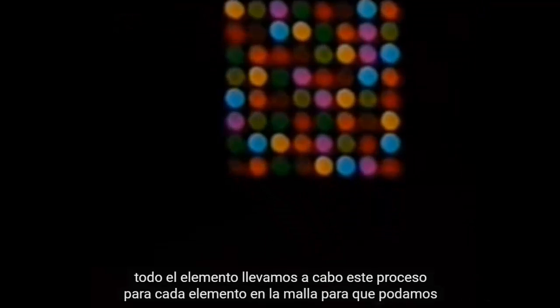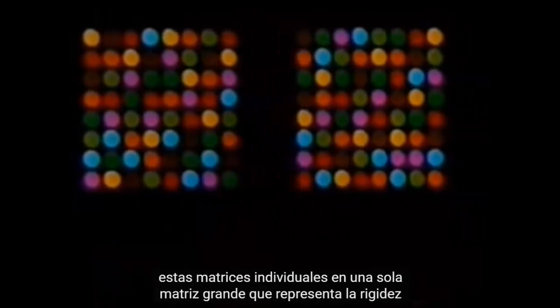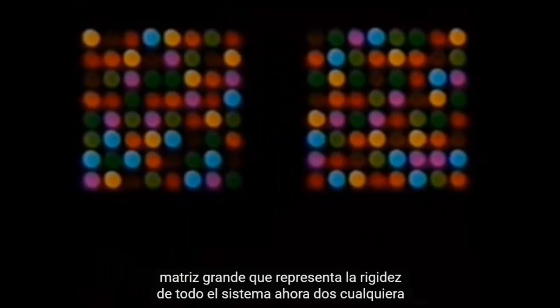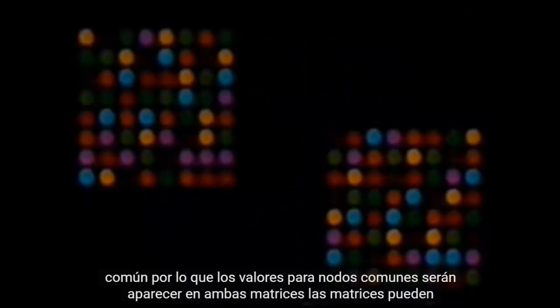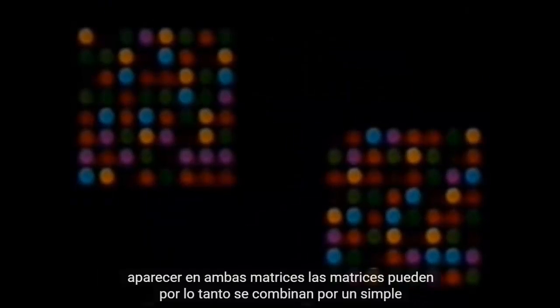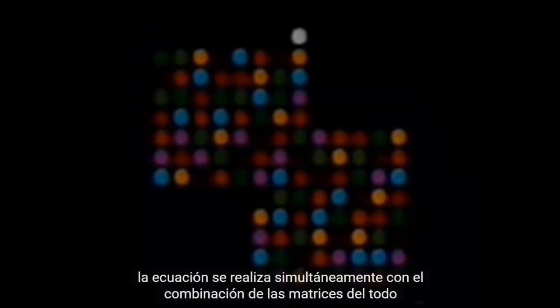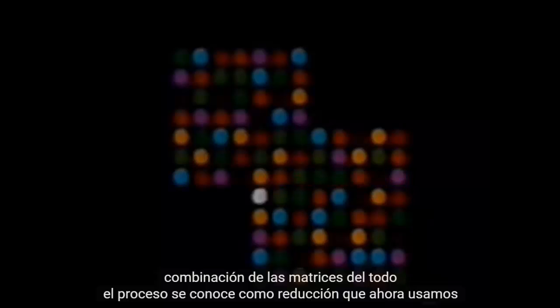We carry out this process for every element in the mesh, so that we now have a stiffness matrix for each one. The important step now is to combine all these individual matrices into a single large matrix representing the stiffness of the whole system. Now, any two neighboring elements will have nodes in common, so values for common nodes will appear in both matrices. The matrices can therefore be combined by a simple merging technique. In practice, the process of solving the overall system equation is done concurrently with the combining of the matrices. The whole process is known as reduction.